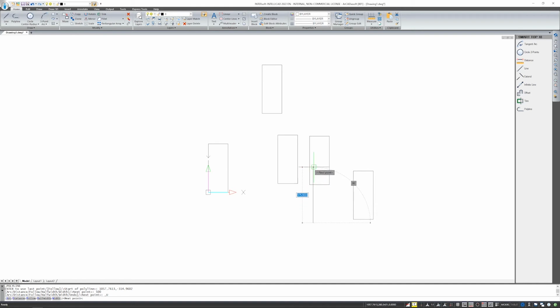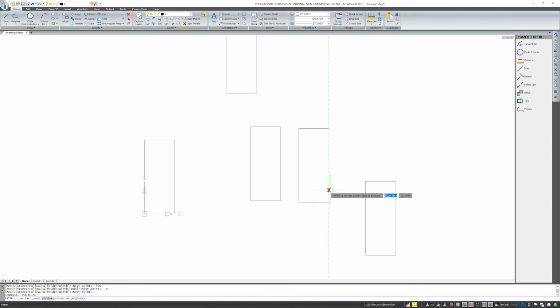You can also introduce such drawing at an angle. You have something like tracking in the program here. Note that when I stop at some element, at some corner, for a moment, then I have the cursor, a green line appears that shows you to start drawing exactly on the same line. This line will appear only when you draw or edit something. It will only appear vertical or horizontally. You need to keep the cursor on one of the lines, and in a moment you can get this line either horizontally or vertically, depending on how you need it.